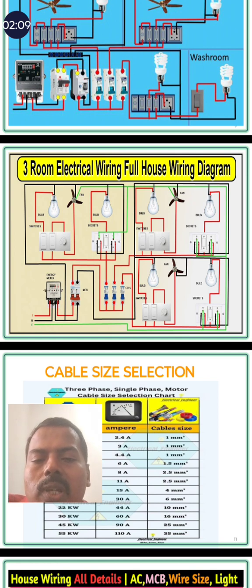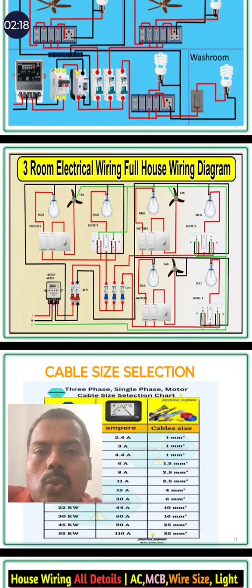Generally, how the electrical system functions is from the electrical steel conductor to the cement pole, 2-line conductor, from the 2-line conductor to the meter box, from the meter box to the main switch. As the main switch, nowadays we are using the MCB, a 3-phase or 2-phase MCB. Based on single phase or 3-phase, from that we connect it to the panel box.